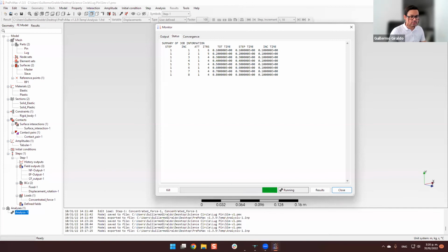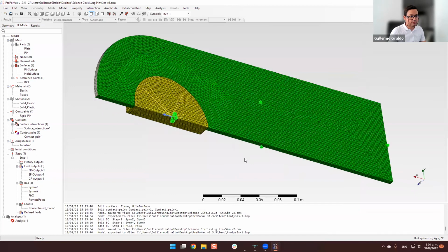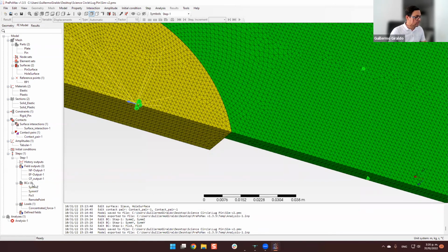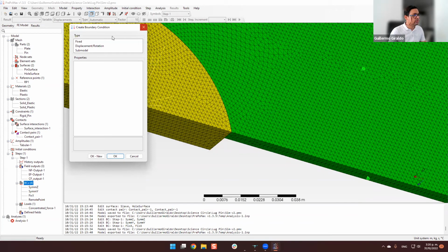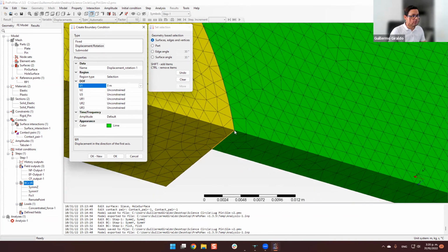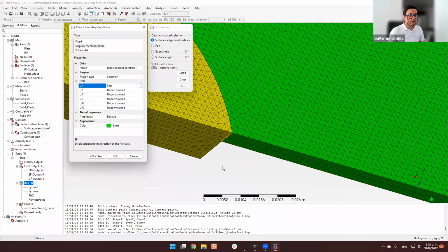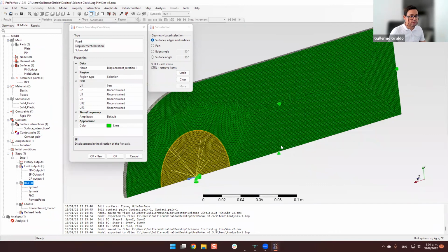The problem is the way these symmetry boundary conditions work. They are not symmetry, because I am not using symmetry; I use a simple displacement boundary condition set to 0. It shouldn't create an over-constrained system of equations, because it should be treated by elimination and not by Lagrange augmentation. If you know what that means. If not, we can start the implementation of FEA.